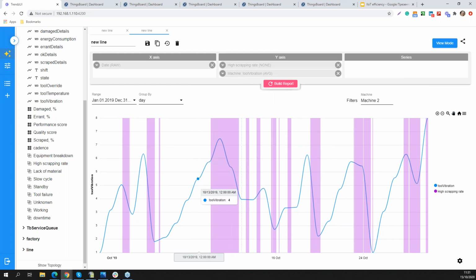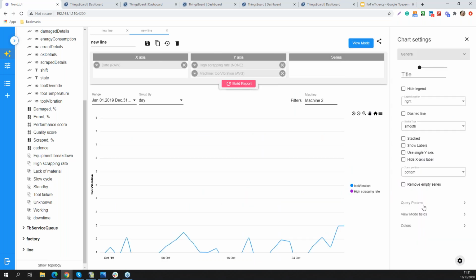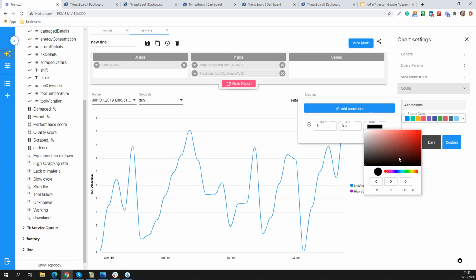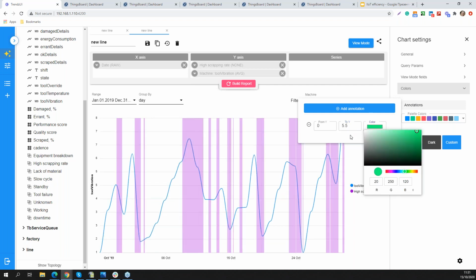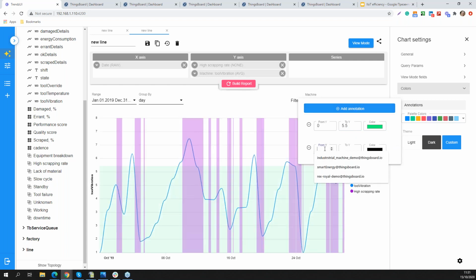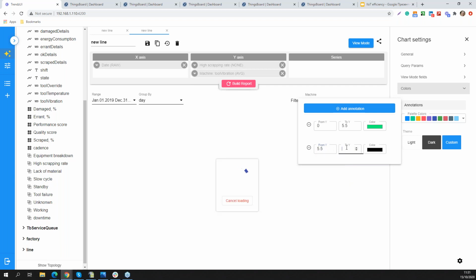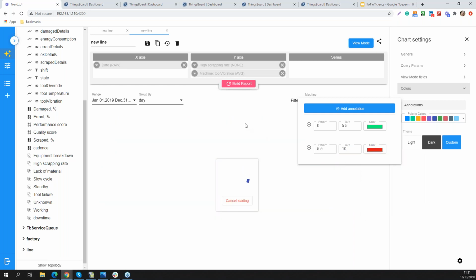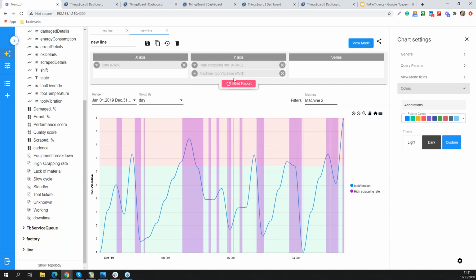the time periods when the vibration was higher than our threshold, and now we're able to see that we're even able to define some color zones to distinguish between these states easily. So you can see them now. We are defining the color zone higher than 5.5 as critical for us. So here we are.